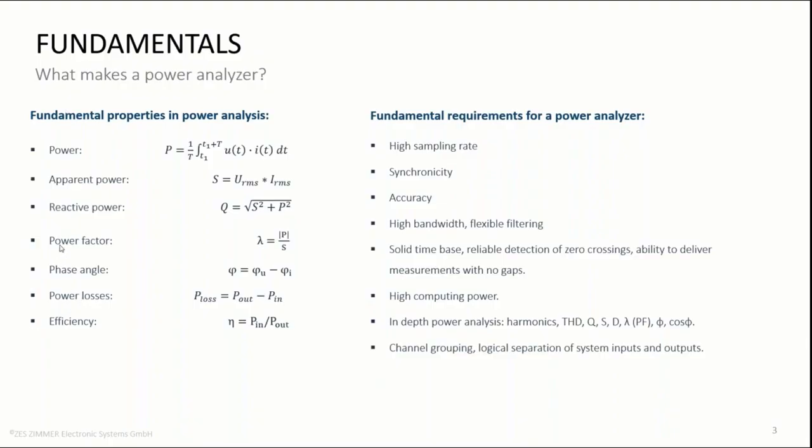These characteristics that I mentioned before, paired with high computing power, will additionally enable the power analyzer to perform further analysis on the transient on power, such as star-delta conversions or the recording of transient states, harmonic analysis, which itself will give further parameters such as phase angle, vector diagrams, THD, distortion power, and more.